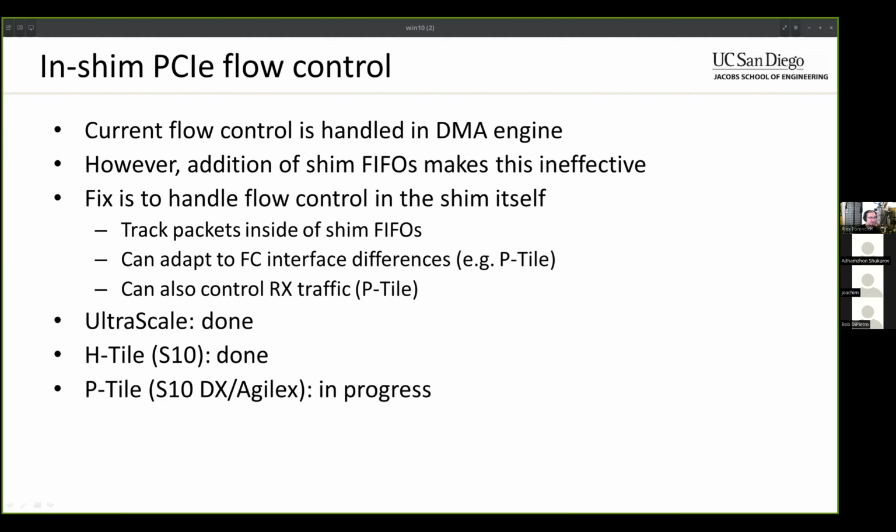And then on the Agilex design, I was seeing low performance, I think because of these other changes, or because of these other parameters in the config.tcl file, and it didn't have anything to do with the flow control. So I think I have it working on the Agilex, but I need to do some more testing to verify that once I change the other parameters and see what happens there. The important thing, though, is the design that I have loaded on the Agilex, it doesn't hang. So that's good. And that implies that I think I'm doing everything correctly in terms of flow control.